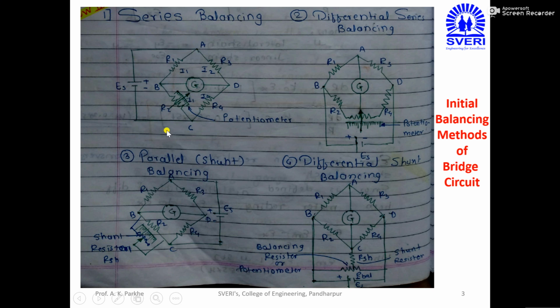If you go through this circuit diagram, again it consists of one Wheatstone bridge circuit having four fixed resistors, that is R1, R2, R3 and R4. Input is given across the terminals A and C. Output is measured across the terminals B and D by using this galvanometer, which is also called a display unit. But sometimes all the resistors are not manufactured with the same resistance value.